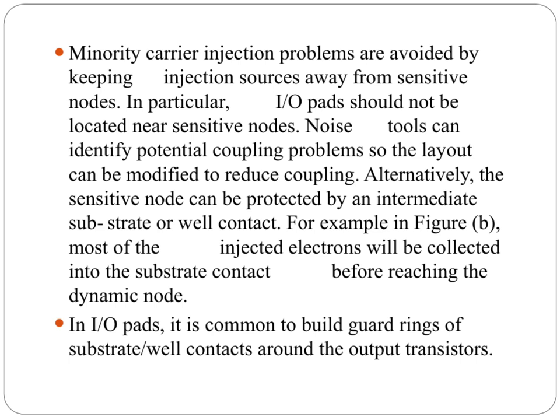Additionally, it's common practice to surround output transistors in I/O pads with guard rings made of substrate or well contacts. These guard rings help further isolate the transistors and reduce noise coupling.